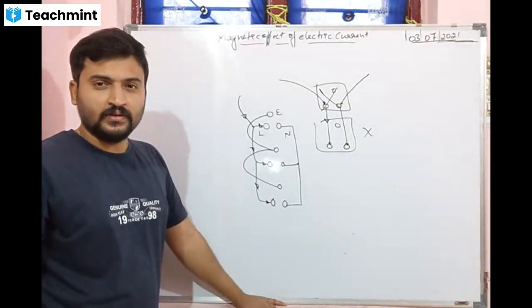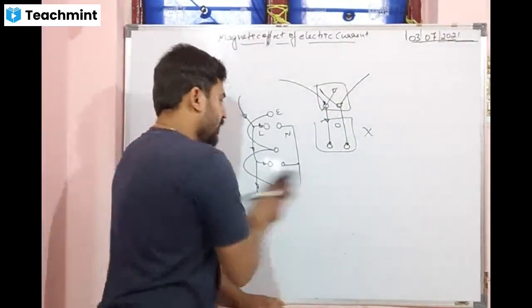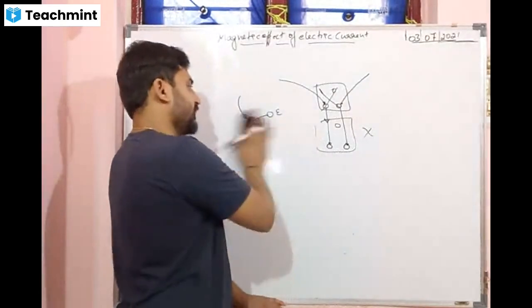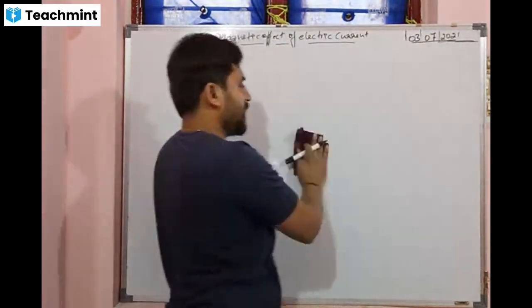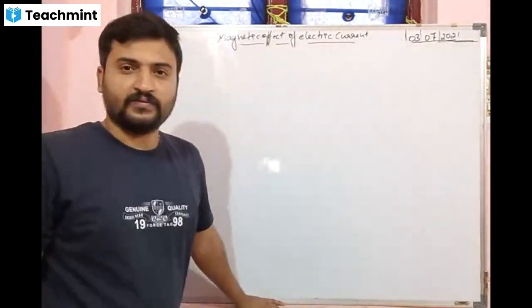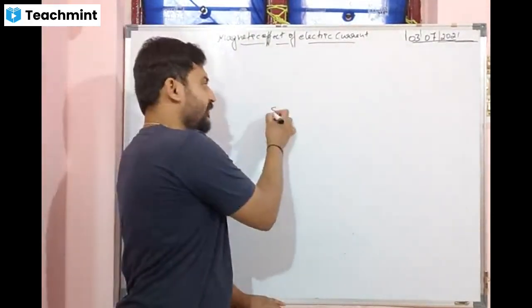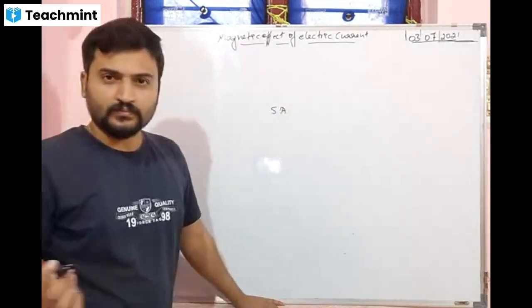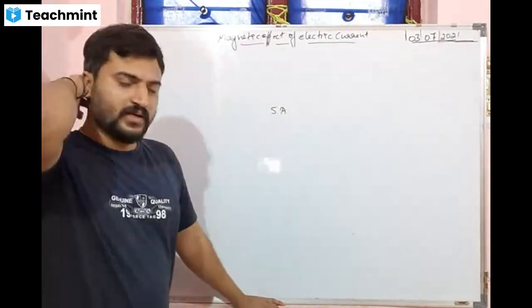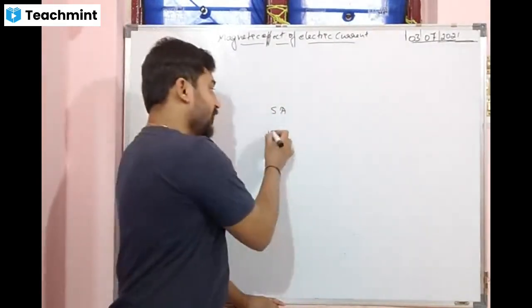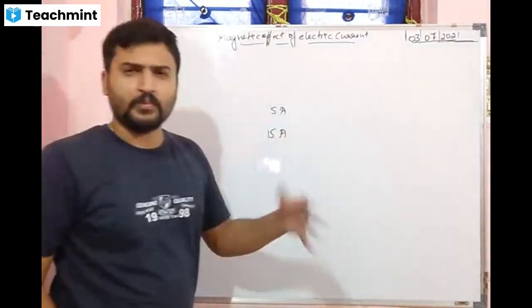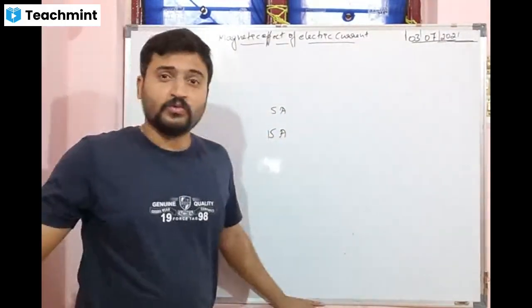Understood? So we connect parallelly and we use fuse for the safety. We use fuse, we use MCB for the safeness. Fuse also you should choose: if it is lighting, 5 ampere. If you are using mixer grinder, geyser and all that, you have to use 15 ampere. Problems may come inside. They may give the problems.